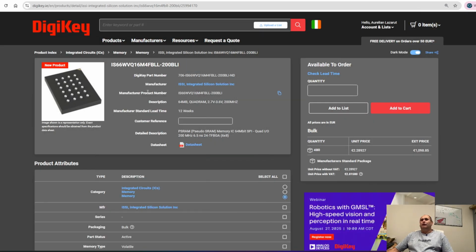Because of this, the way access to this memory works is you present data in chunks of 4 bits. So you present the address in chunks of 4 bits, and then you present the command, whether you want to read or write. And of course, there's going to be a penalty for this. It will add to latency. I can live with that, and I'll come to reasoning about latency as well.